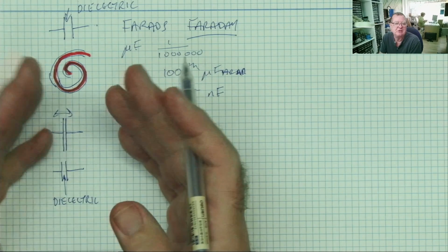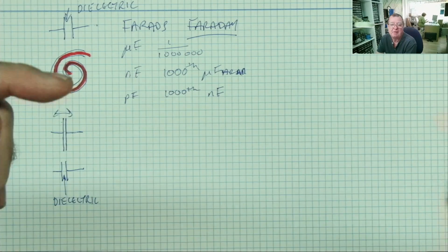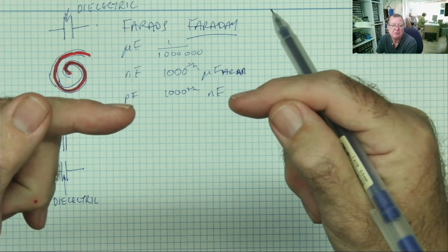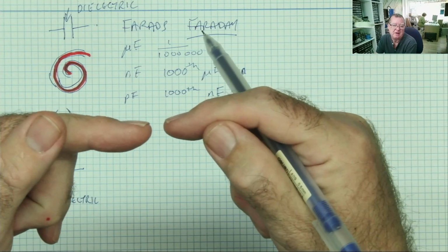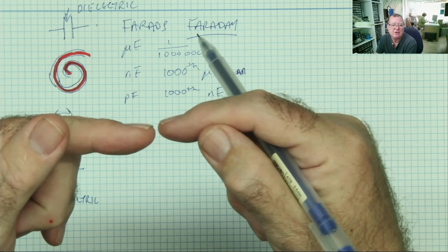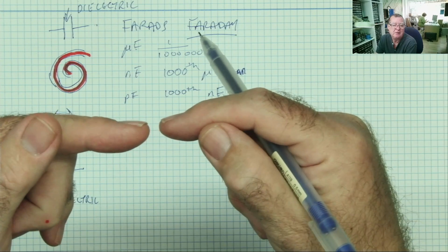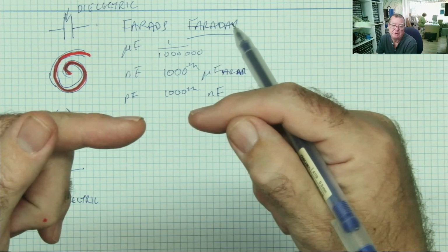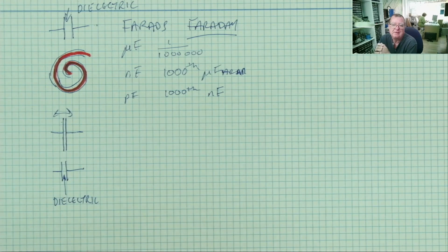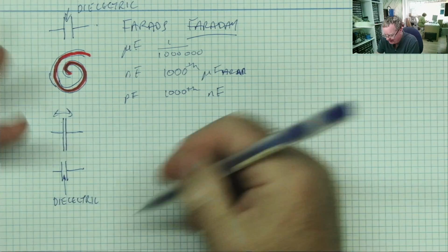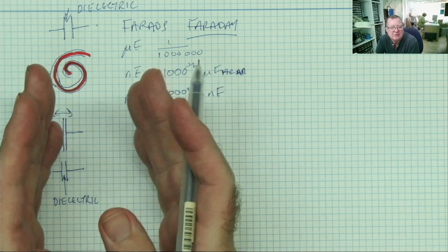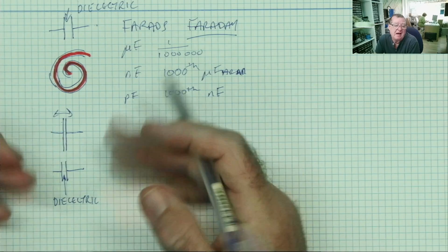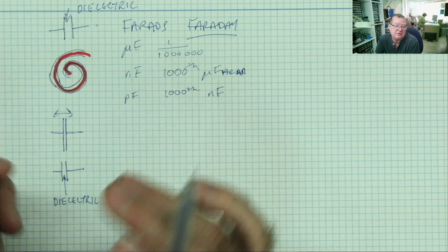I mean, if we use air as a dielectric, which we could do, you can have high voltage on two probes and nothing happens. But as you get closer and closer and closer, and you've seen this in Frankenstein films and such like, no doubt, at a certain point the air will arc over and you now have a breakdown of the dielectric. In fact, once it's arced over, you can move them further apart because it'll continue to arc over. That's something else. But anyway, that is the point. The closer together the metal plates, the lower the voltage you can withstand. Again, that will depend to some extent on the type of dielectric.